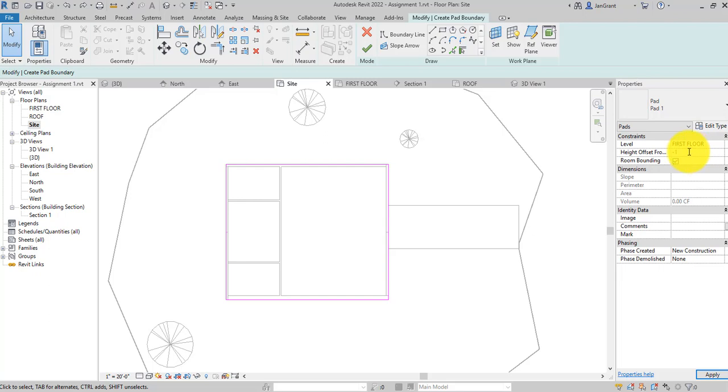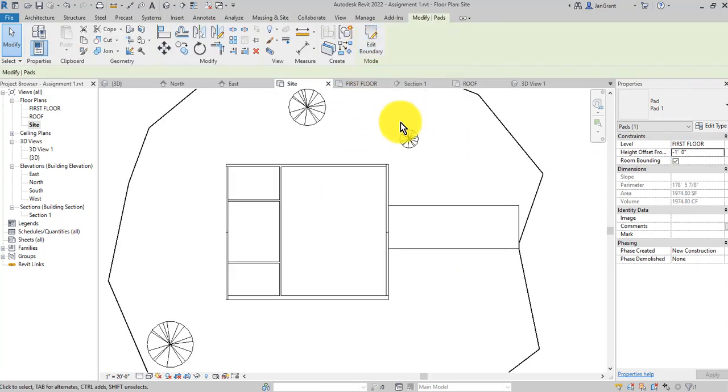Now, if you have a building that's shaped with like an L shape, or maybe have some curves in it, you can use some of these other tools to create that building pad. One of my favorites sometimes is called Pick Lines, where it actually picks the lines for you, so you don't have to try to draw those curved walls. We'll use this later as we look at other tools, and also pick walls or pick lines. Okay, the other thing, now we're done with this, the height, and we established where it was. We can pick the green check mark right there.